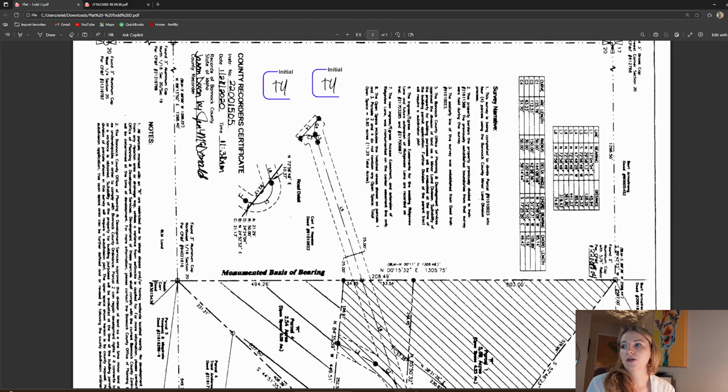So if I were reading this one, it says 34, I want to say it says 50, and then that could be 06 or it could be 08. It's really hard to tell. But at the very end here, that's not going to change your bearing a ton, but when the number is closer to the front in your curve table, it can make a dramatic change in the whole layout.